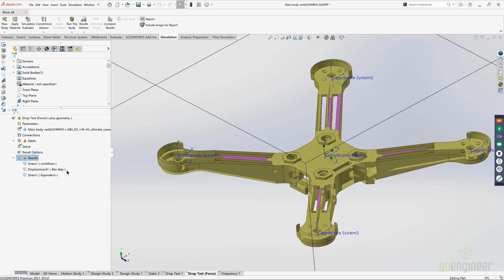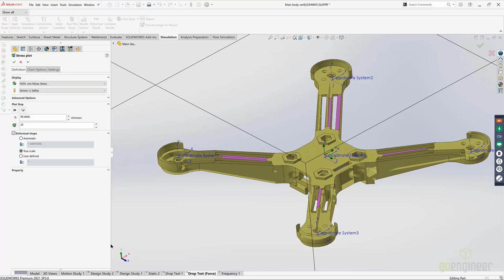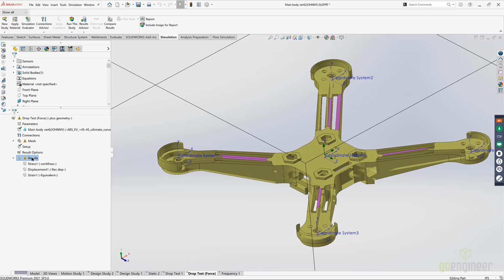Unfortunately, I did run the analysis, but after you run the design study, since I pulled some things out of there and the model has changed, the results have to be rerun. So I'm just going to show you the options. Here we can make a von Mises stress, just the stress over the entire model. We can do stresses in XYZ, principal stress, all that great stuff. Another tidbit is you can pull the list of stresses, displacements, and interaction friction forces.